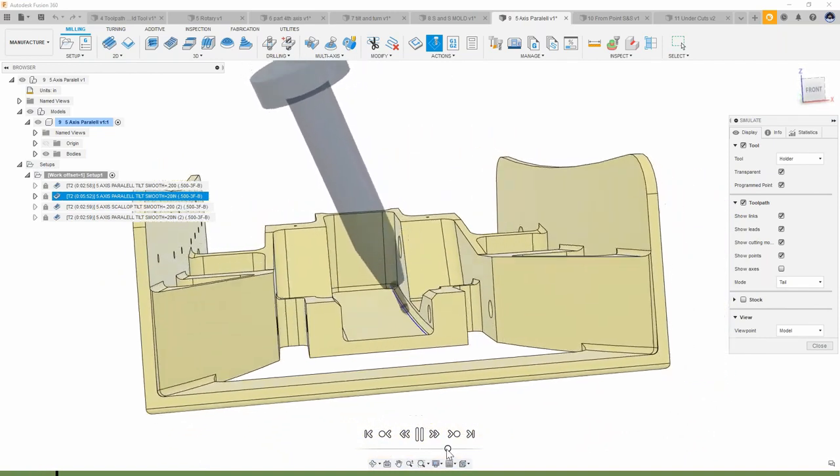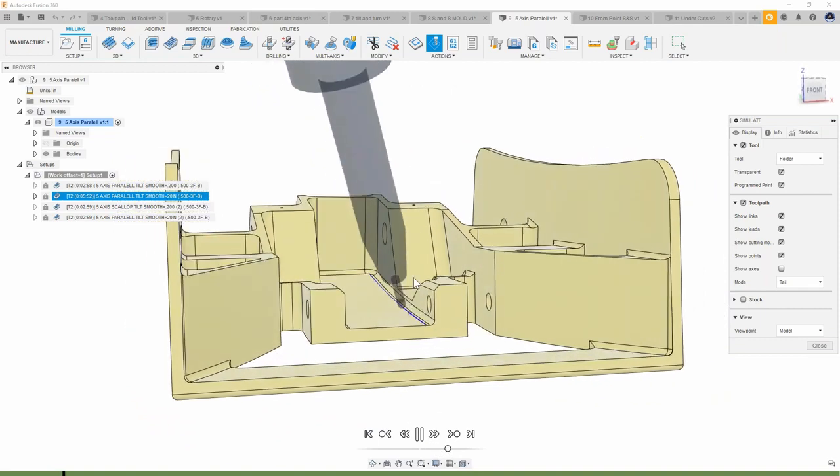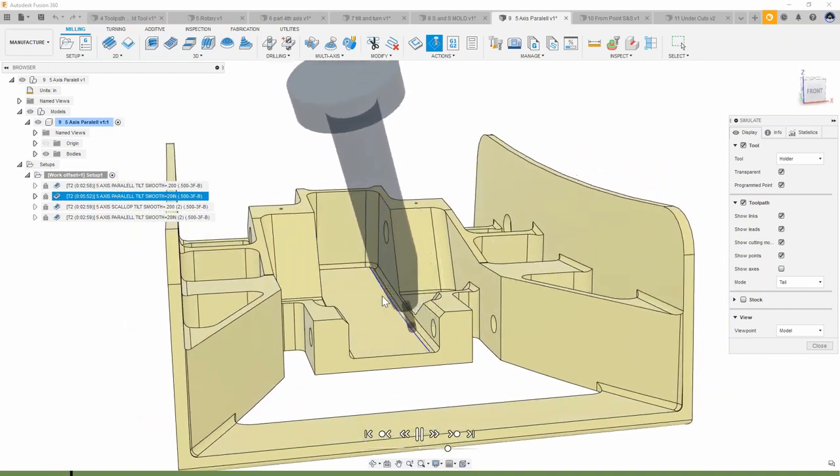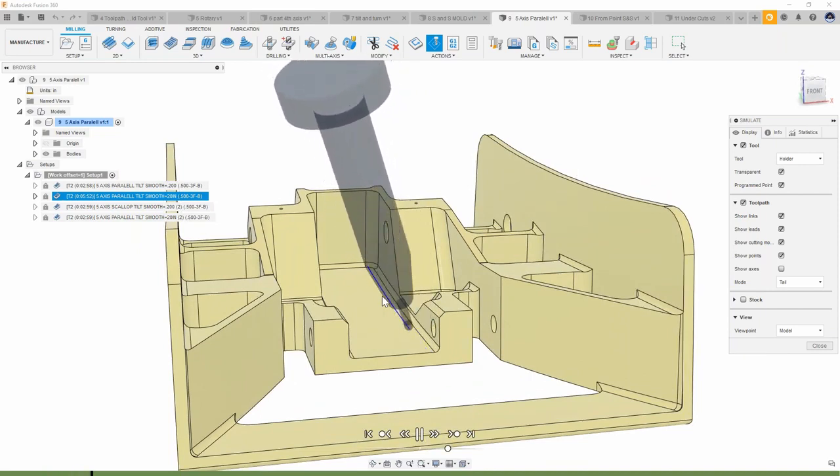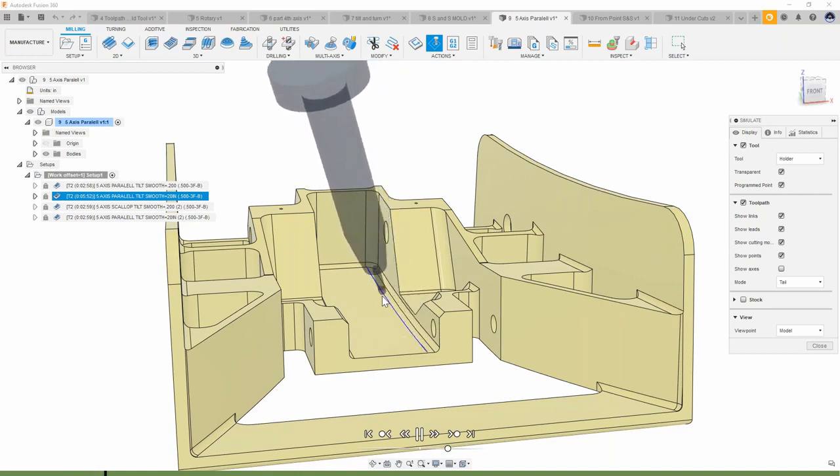The other thing is, obviously we love 5-axis, right? I love putting 5-axis stuff on Instagram, things like that. But with the caveat of if you don't have to do it, let's not do it. When we do introduce all 5 of our rotaries moving at one time, what happens is we get volumetric error, and really we're limited by our slowest axis on the machine, which is most likely one of our rotaries.